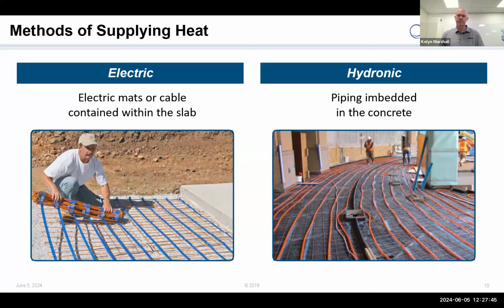And if you do a small area, say 1,000 square feet for a driveway, the majority of the cost is in the mechanical room. And there really isn't a large cost jump in boiler sizes at that size. So if you go from a 50,000 BTU boiler to a 75,000 BTU boiler, there isn't a huge price difference in that mechanical room. It's taking the lion's share.